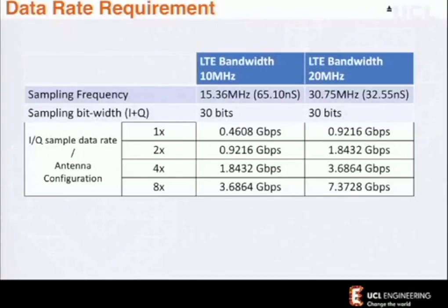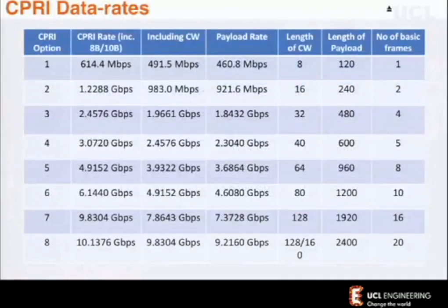So, although we're talking about compression, and there's a lot of good work starting, these are going to have to be very fast compression algorithms. And so we're unlikely to see the same sorts of compression rates that we get for MPEG encoding, those very high, 20 to 1 and above type compression. I think we'll have to go some to find those, purely because usually to get high compression, you take a large amount of data in any one time. That's usually how you do it. You have to grow the amount of data you take because you need to spot patterns within it. We're probably not going to be able to do that because of the latency that then adds into the system.